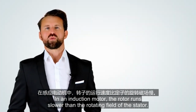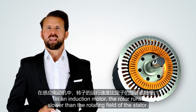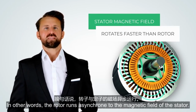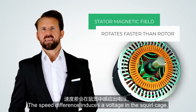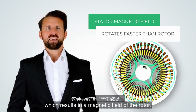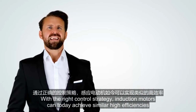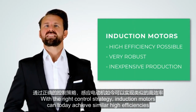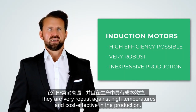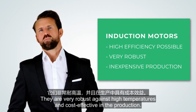In an induction motor, the rotor runs slower than the rotating field of the stator. In other words, the rotor runs asynchronous to the magnetic field of the stator. The speed difference induces a voltage in the squirrel cage, which results in a magnetic field of the rotor. With the right control strategy, induction motors can today achieve similarly high efficiencies as motors with permanent magnets. They are very robust against high temperatures and cost-effective in production.